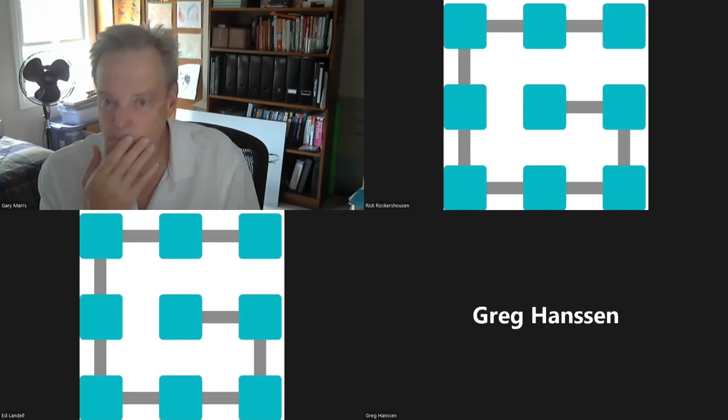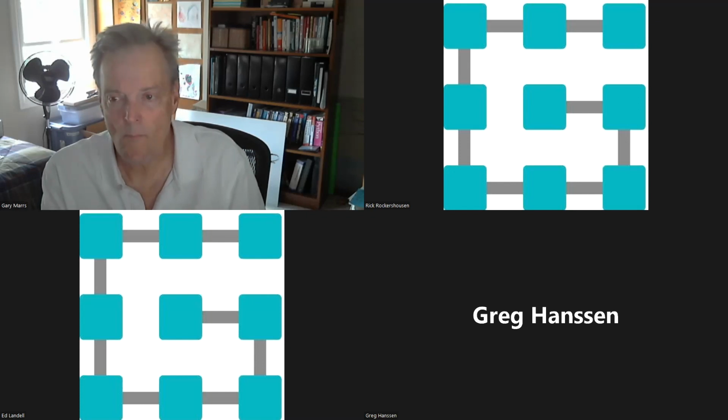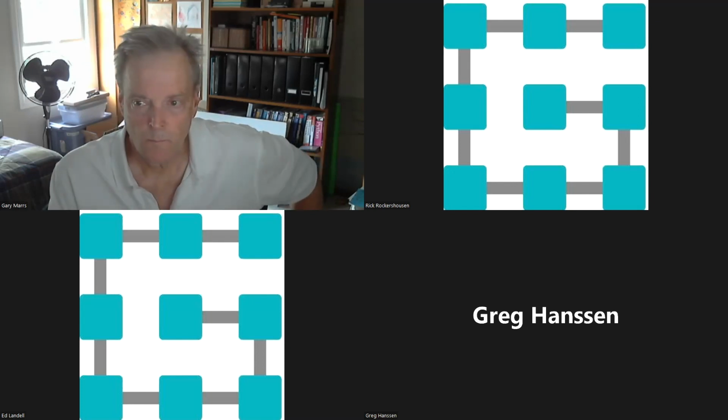Well, no, getting a lot of echo here. As you said, Greg, the whole point of it is, the ACK is part of the protocol. Are you sure the bit rate was set correctly? And the sample point? Yeah, everything was fine. I mean, I tried. Sample point? Yeah, I was. Well, I haven't really. I'm assuming that's been working okay.